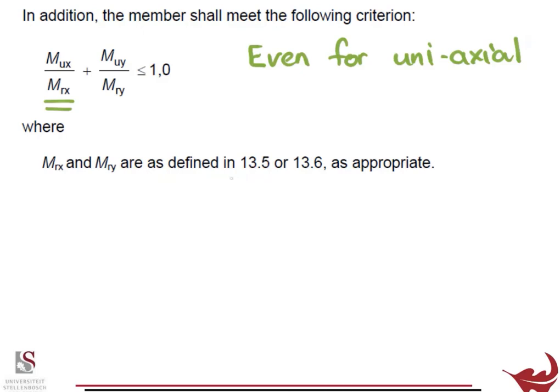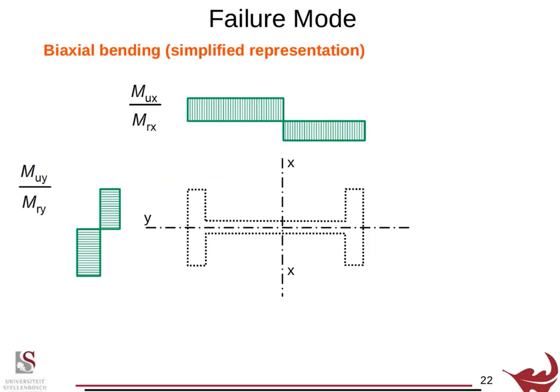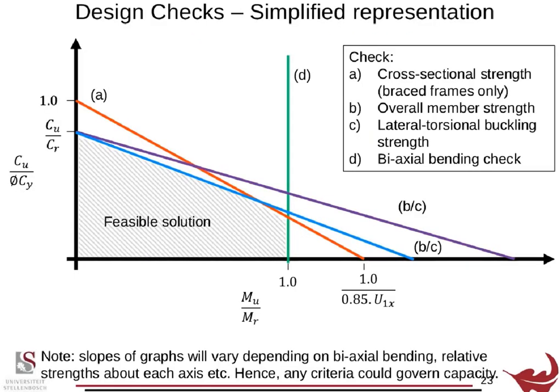And as I said, you do this as required: you design the member as it is. If it's laterally restrained, design it as laterally restrained. If it's laterally unrestrained, which in most cases it is, design it as laterally unrestrained. And so we're just checking stresses in this case, or capacities. We're making sure that the interaction of only moment is not going to fail our beam.